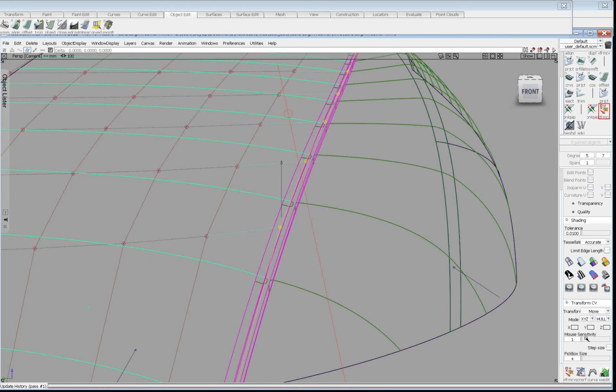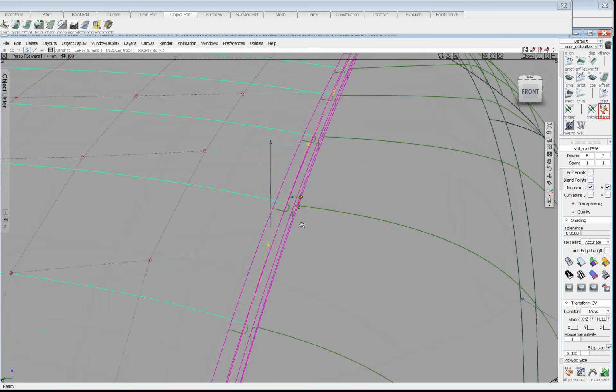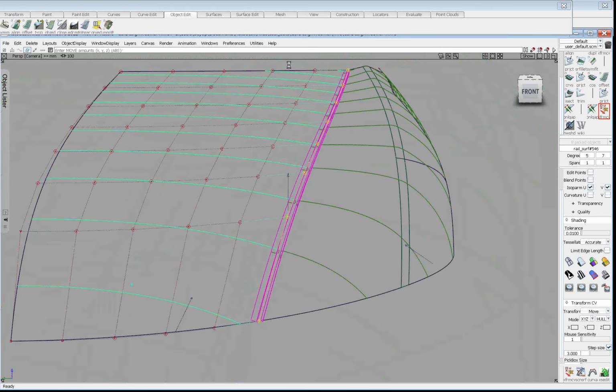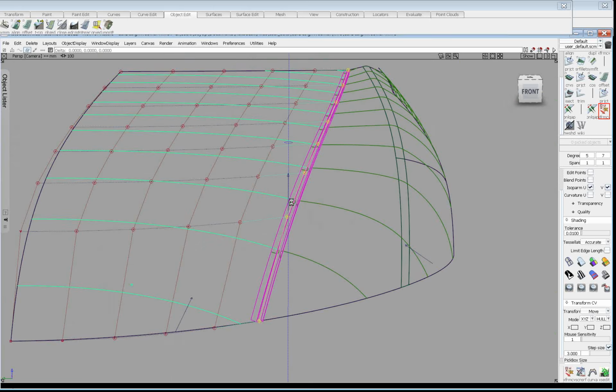What I'm going to do is come back and detail this a bit more by putting in a step size, and we'll just make it a fairly big shingle across here. But now we're going to just say, let's move that up 3 millimeters. And you'll see that the panel gap actually continues to update, even though I've made a modification to the offset here. Let's take a look.